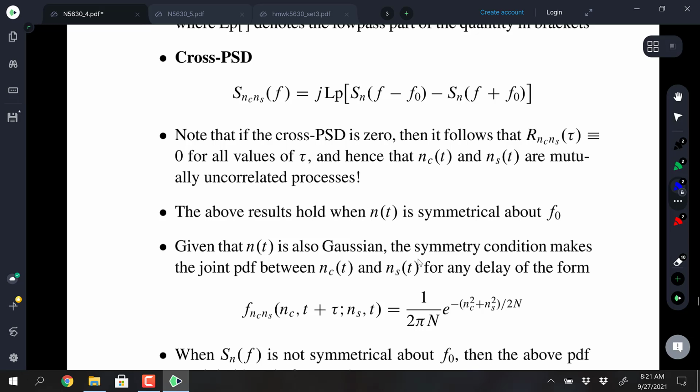The thing that we'll have to keep in mind, if you're going to be doing this stuff on the job, is that there's so much that goes on with digital comm these days. You'll be looking at a spectrum analyzer, you'll see the received signal, you might put in some additive noise to perturb it, and you want to measure the noise power at the receiver front end. Then you'll get into the receiver, down convert it, and it will be at complex baseband, because that's the way digital comms works with DSP. And then you'll get into an issue at some point where you're trying to reconcile the scaling and the noise power levels and things like that.